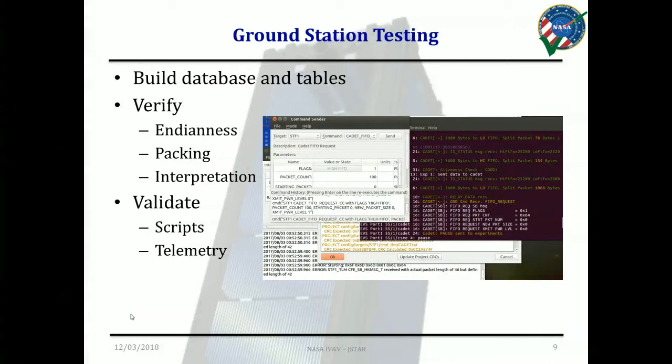So at the next step, when we had an actual CADET radio simulation, it showed that all the data flow through commanding and the telemetry going back into the buffers in the radio and coming to ground all happened appropriately. Those are some of the other kinds of tests we did. So we're building up more of an end-to-end testing suite all within software. Of course, this doesn't alleviate the hardware testing that we did after that as well, but it helps get you further along that path and lets multiple people run the software simulations and do that kind of testing, which you wouldn't necessarily be able to do since we have a single string of hardware.